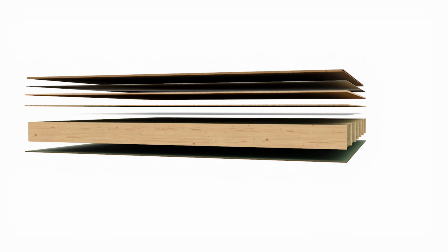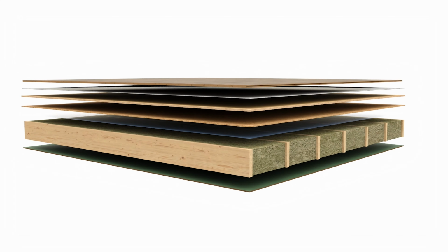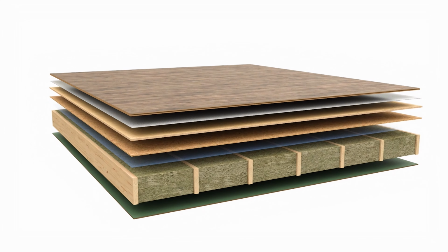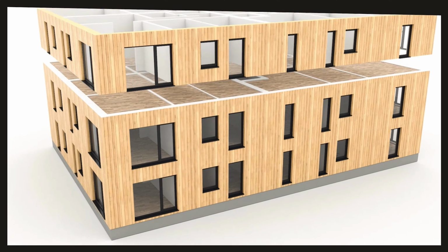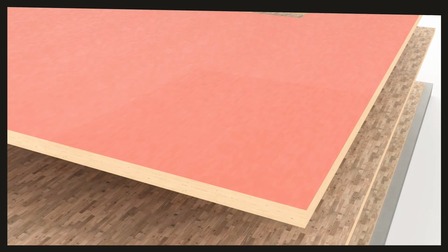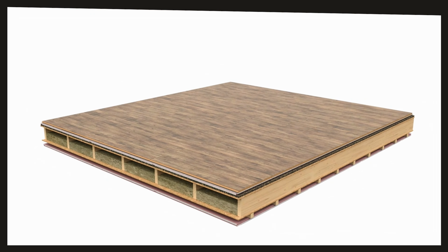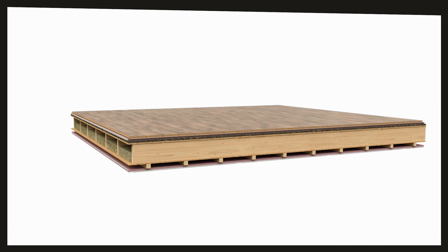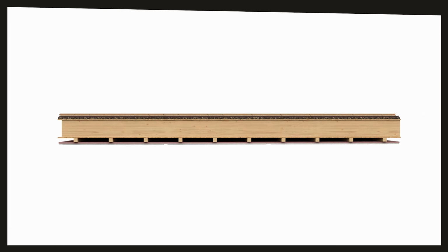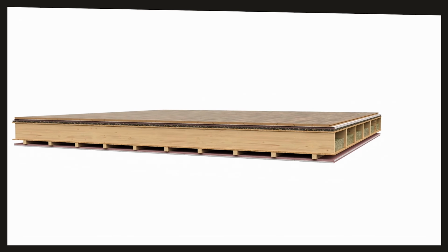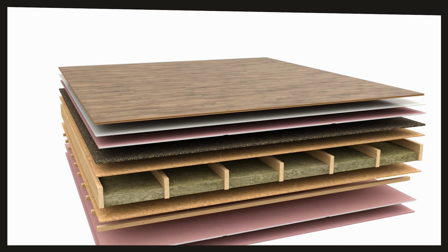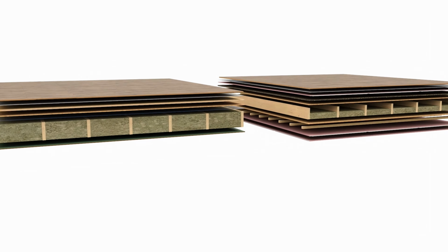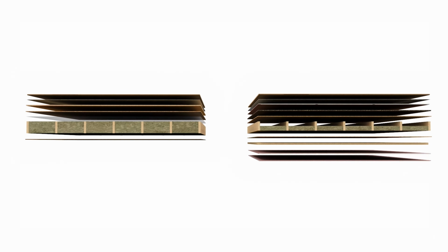As the lowest floor of a building, it also requires significant insulation to prevent heat loss, and moisture proofing is crucial to prevent any moisture from entering the building. Intermediate floors are any floors situated between the ground floor and the topmost floors. The intermediate floors are designed to distribute loads efficiently to the building's structural framework. Compared to ground floors, thermal insulation is less critical, but it requires insulation primarily for soundproofing between the floors. Therefore, the first floor floor differs significantly from intermediate floors, and the construction materials may also vary.